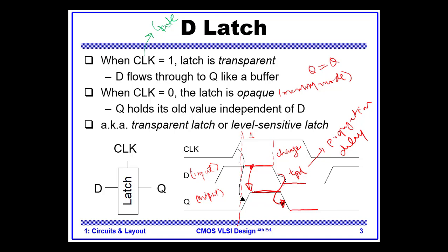But let's see what happens when the gate changes to 0. So at this point the clock becomes 0. Okay, and at this point the latch moves to memory mode. What that means is whatever is at the output will stay at the output. So we have a 0 at the output and it will stay as 0.